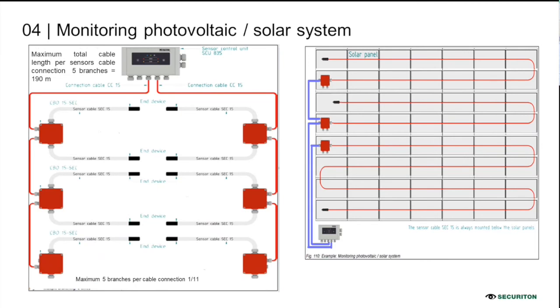As I mentioned earlier, one of the flexibilities is that we can also have branches. Of course, when we start having branches, it reduces the distance that it can cover, but actually you can have 5 branches in a total of 150 meters. So if customers are interested in zoning it because they don't want to have more failures, you can also have a junction box. Or in terms of flexibility, sometimes you don't want to run the same cabling throughout a few areas, and there are restrictions in the grid so that you cannot continue.